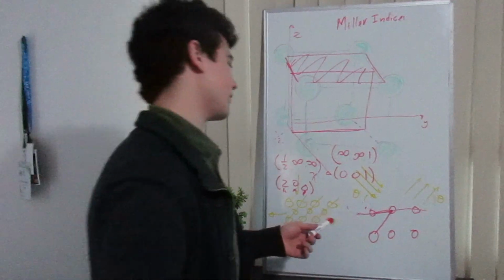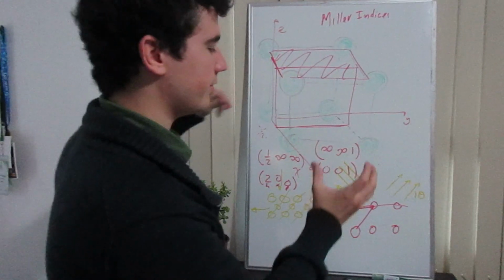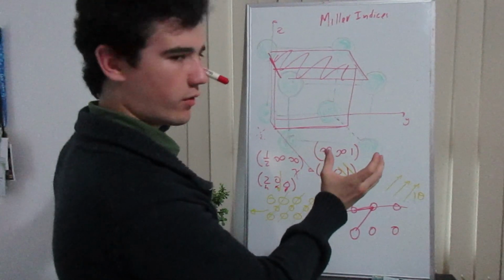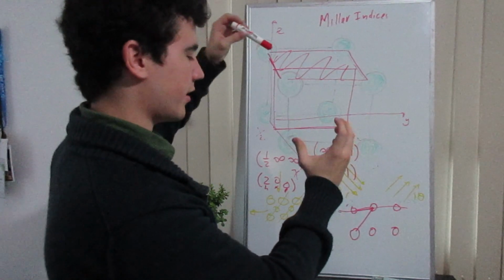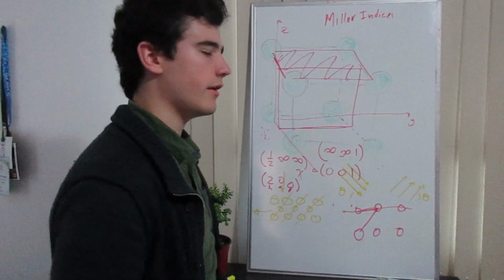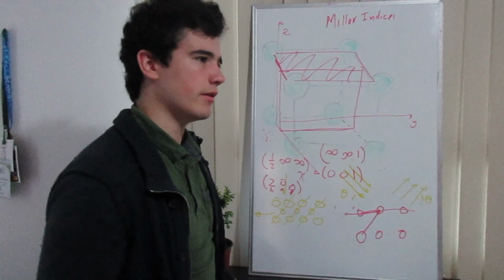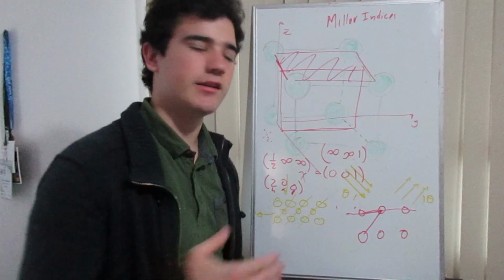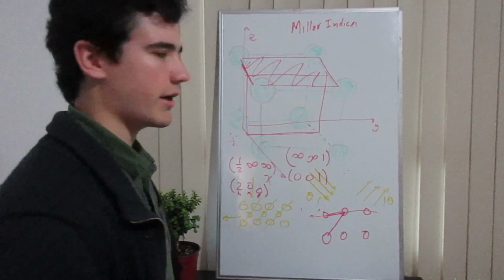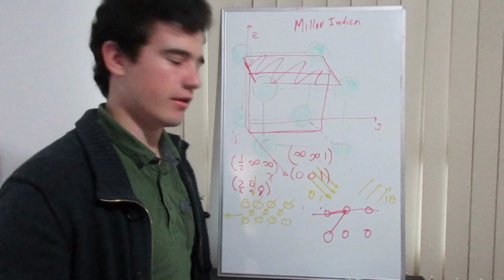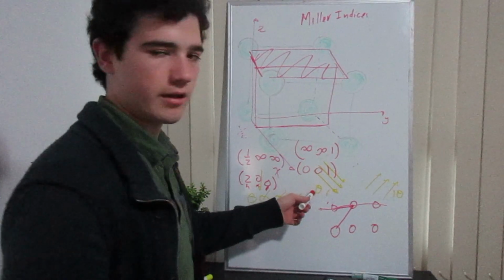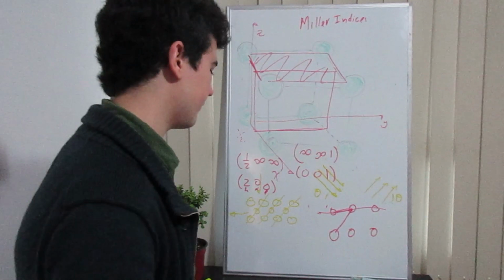So in the experiment, we have the crystal and the emitter of X-rays, and they are both rotating, so that we can see all the angles, and thus we can get the plane density that is the highest for each crystal. So we can identify then the type of unit cell according to the intensity and the angle that is emitted.